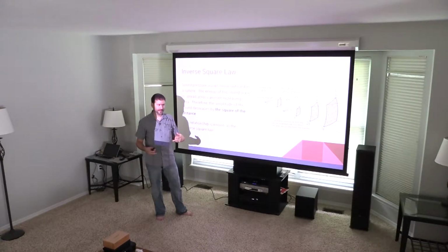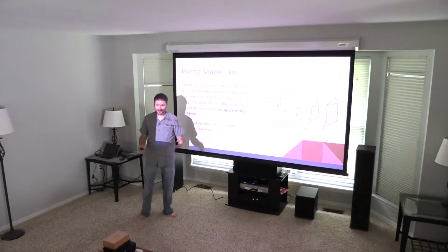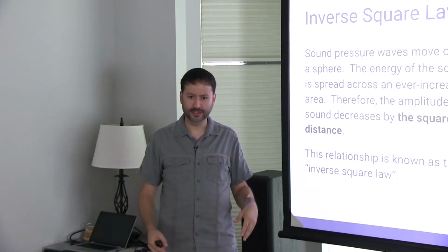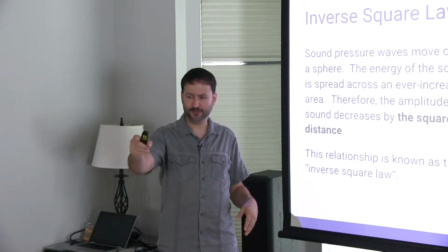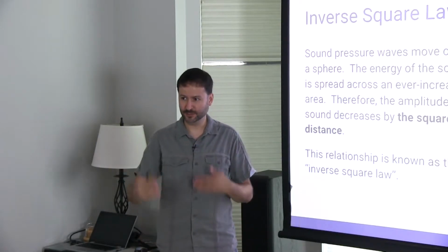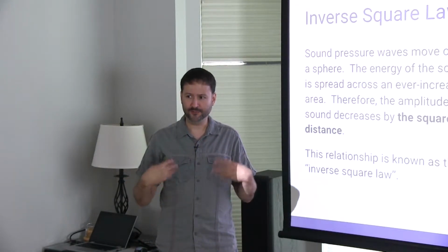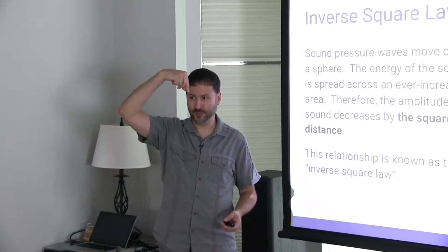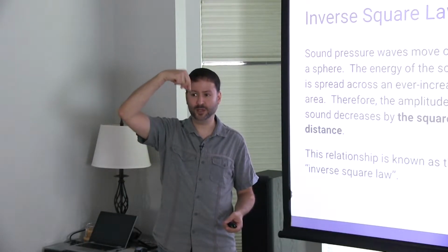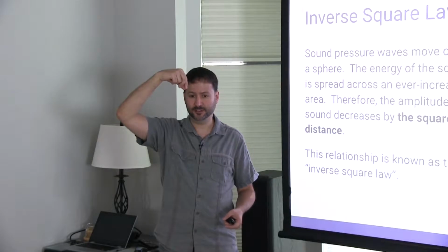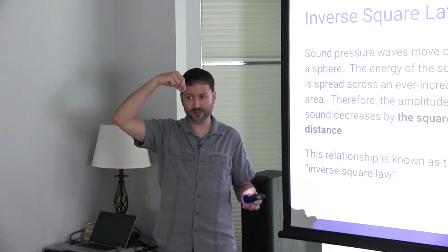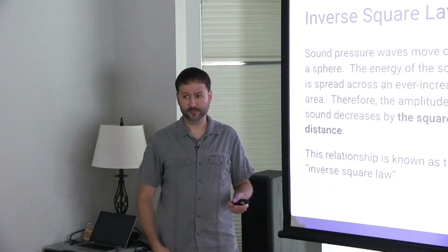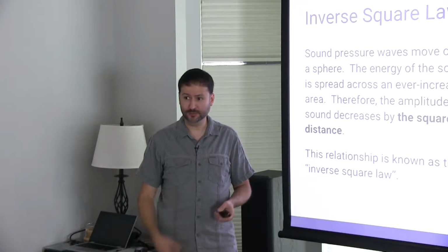The same thing applies with the microphone. If I have a room with background noise and reflections off the wall, and I'm recording from the camera's location, which is pretty far, my voice is competing with all the background sound. But if I put a mic right up close to me, the background sound hasn't changed, but now my voice is way, way louder at that microphone. And so now there's no competition. The background noise is there, but it's so quiet relative to my voice that it's very good.